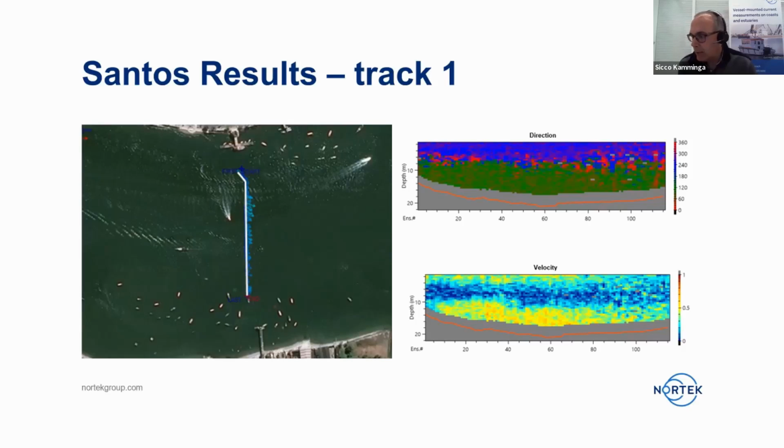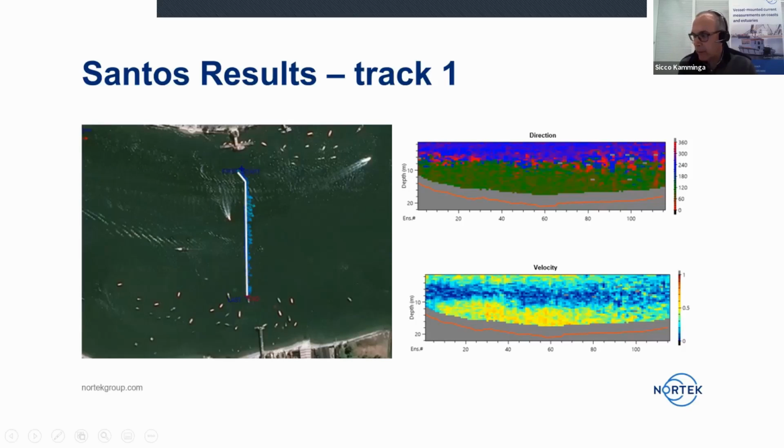In the red line on the lower part, you will see the depth, how deep it is. That is measured with the vertical beam, as Herman just explained. And then in color, you see the speeds. And that's funny here, that on the lower layer in yellowish and even some reddish, the speeds are much higher. Those are going up to like 0.7 meters a second. That's the speed of the water.